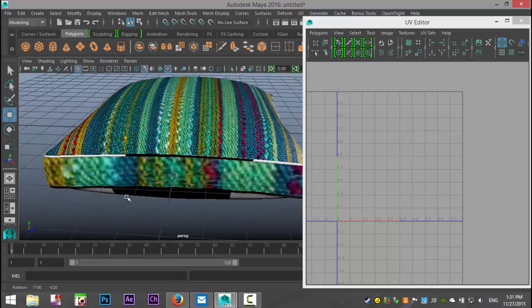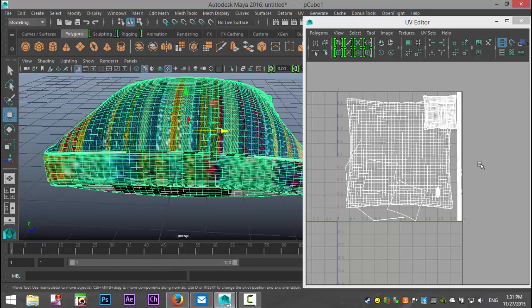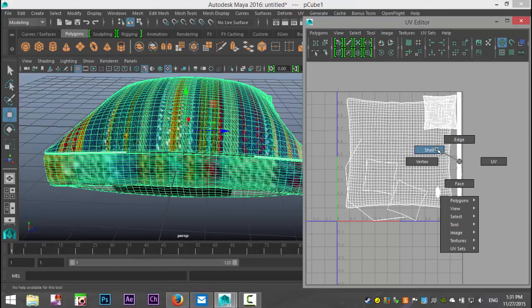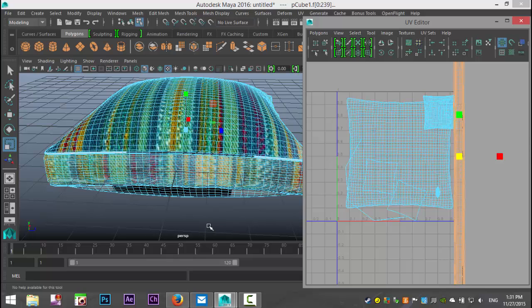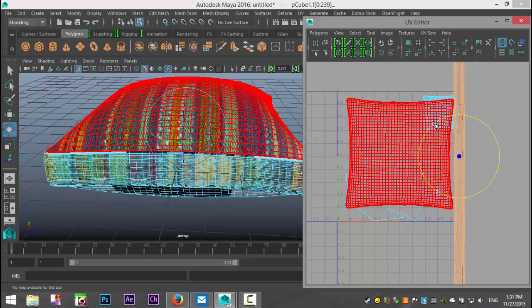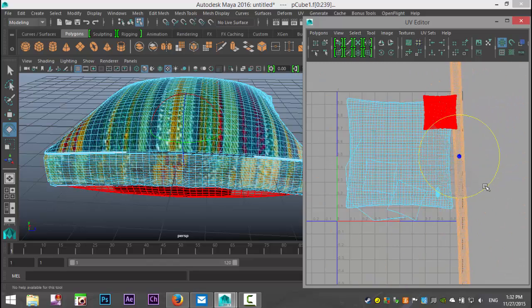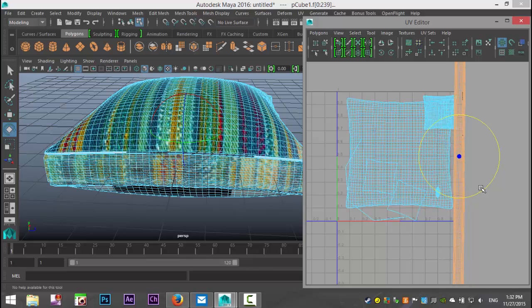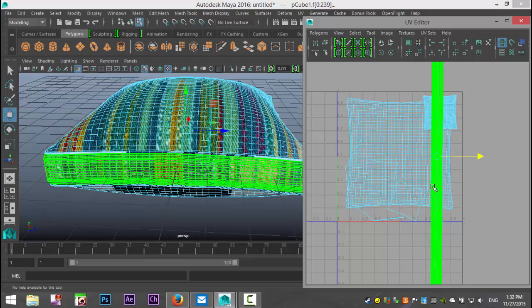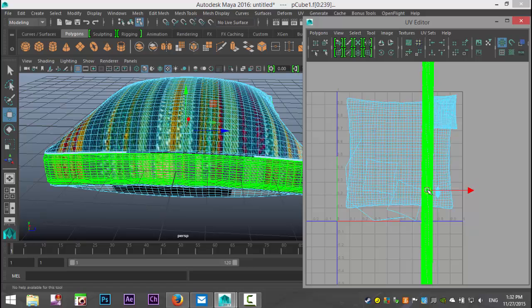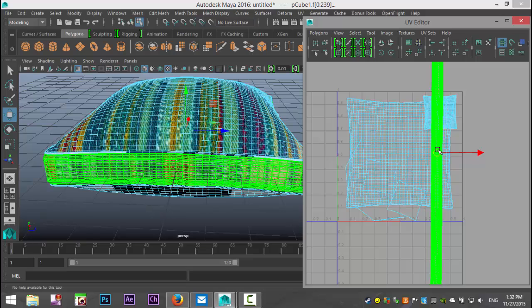Our texture is a bit rough. So we're going to select it. And we're going to hit R. We're going to start to scale that a little bit, preferably in a way that it will line up. So we're going to rotate it all the way around. And then we're going to hit W and move it up until we get the closest match possible that we can get.